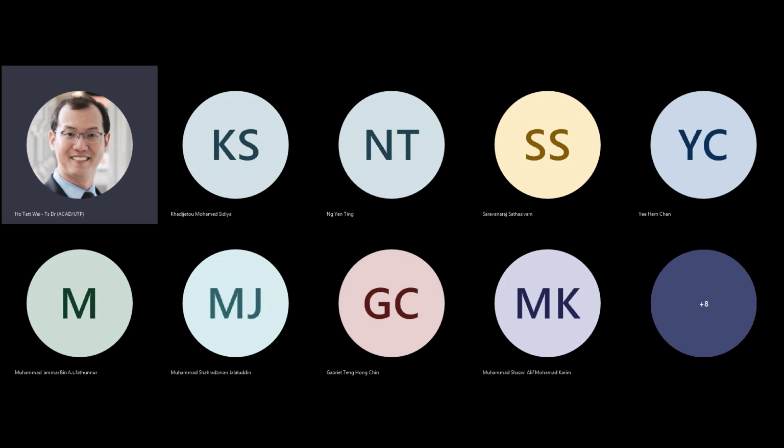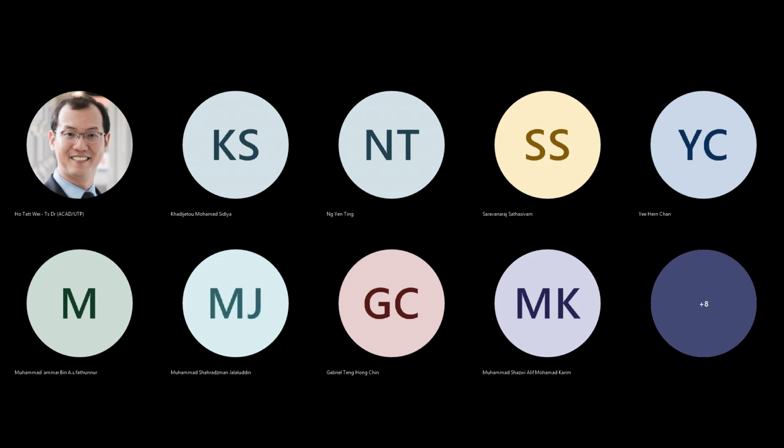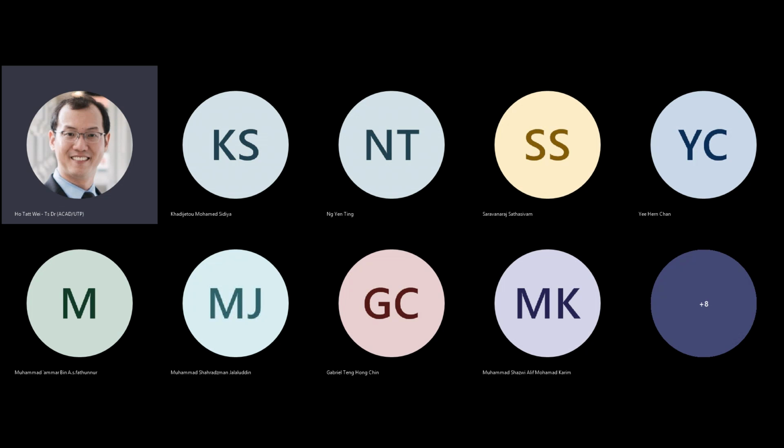And we're looking at the digital logic in the region between two subsequent D flip-flops, all of them in the circuit. In each of these blocks, we're trying to find where the logic path with the longest delay is. And overall, for the entire circuit, there's going to be one or two or a few paths with the longest propagation delay.